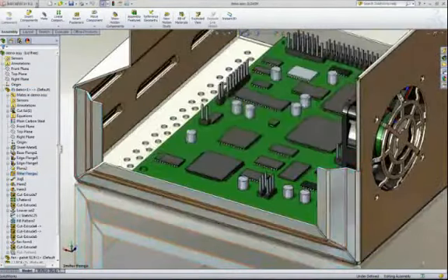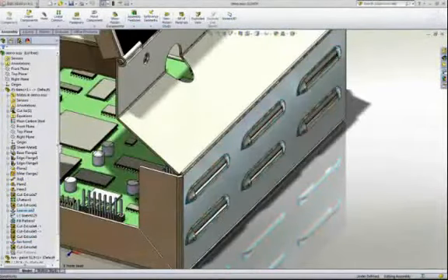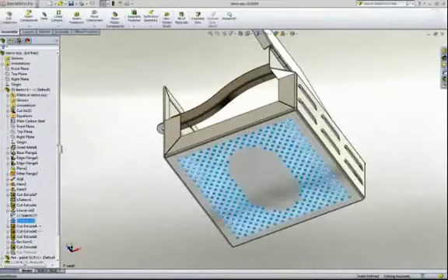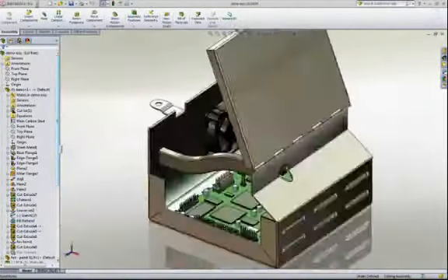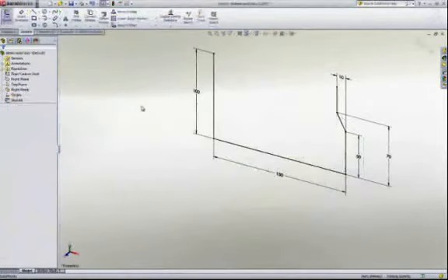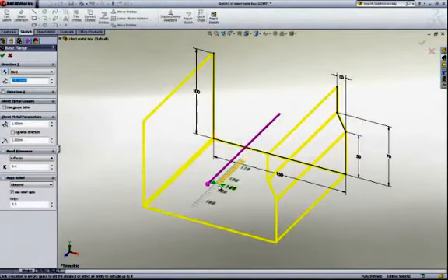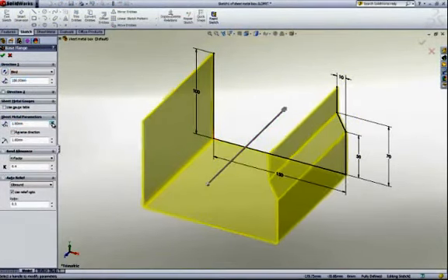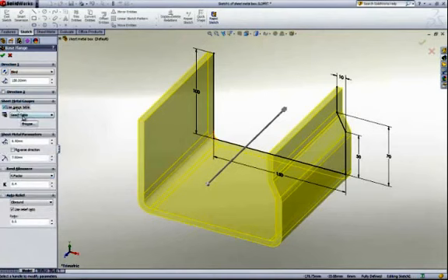Your CAD tool should not limit your creativity. You need the flexibility to create sheet metal parts in the manner best suited to the job in hand. We'll look at top-down assembly design later, but for now, we'll concentrate on the basics. Material selection should be your first consideration. In sheet metal design, we are often forced to adhere to certain requirements, such as standard materials and in-house standards for manufacturing and tooling. You need a simple way to make sure you comply with those standards.